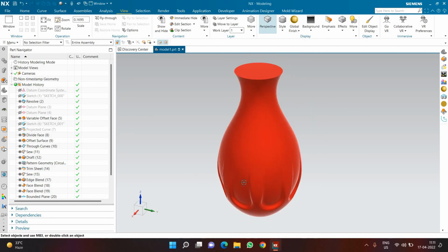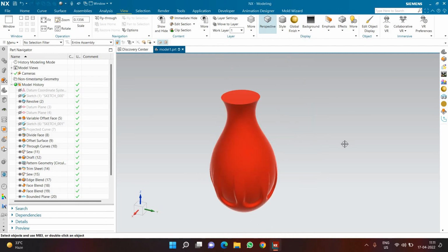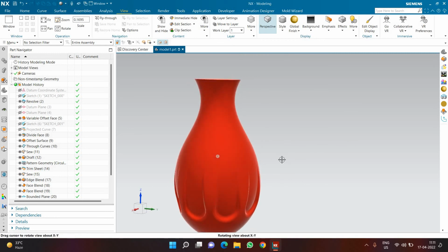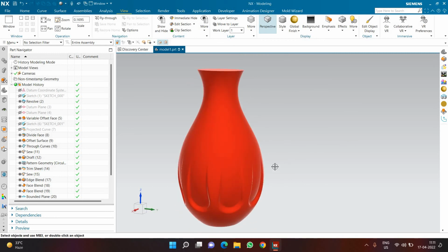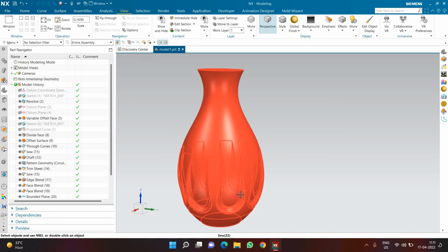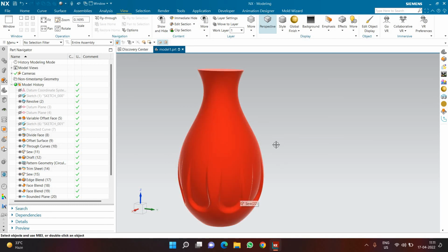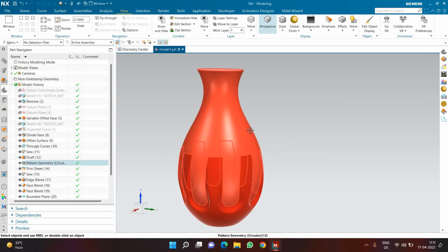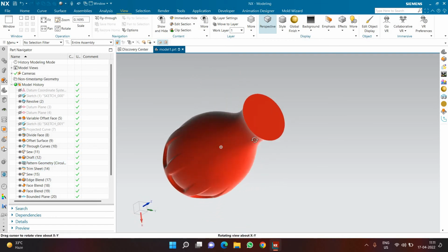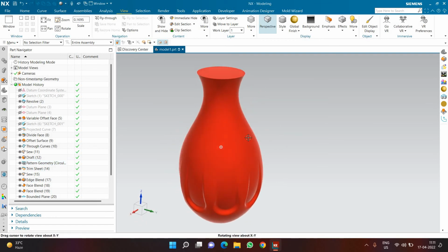The only area where we got stuck was the blend tool, specifically in this area. It can happen with you, it might not. That totally depends upon the kind of configuration you are using. I might not have reset the through curve command, so the surface output I was getting was not very smooth. That totally depends upon what results you are getting. Slight changes in the settings can give you different results.